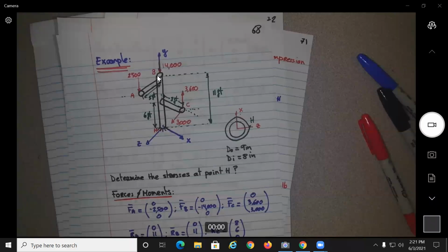Okay? After doing that, you could calculate what would be the deformation at this point and this point. And then you can find the deformation. I don't know if you follow. Then you can assume this one to just be fixed, no? So you can find what will be the deformation in this direction. You can add the deformation just of this piece here by assuming this is fixed, plus the one you calculated before, if we give you some type of approximation. But it would just be an approximation because it would not take into consideration the shear.